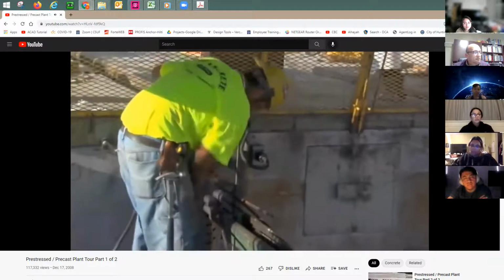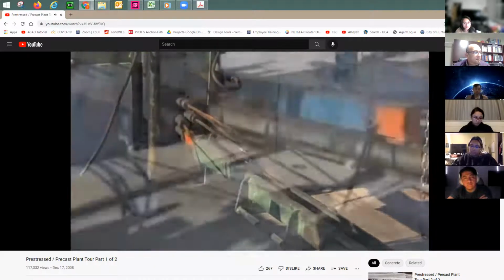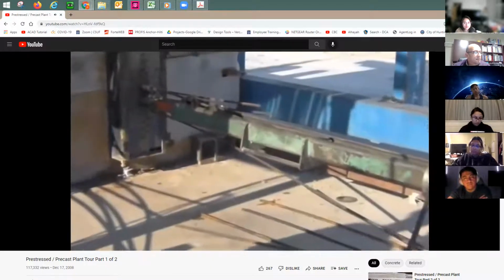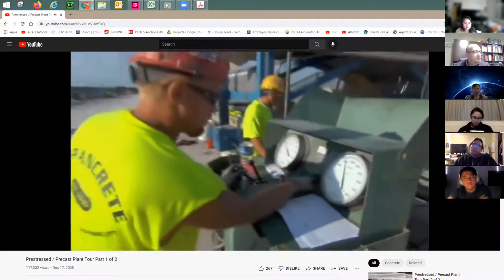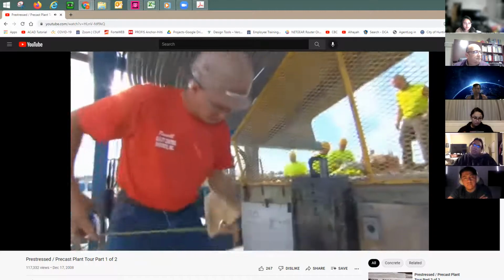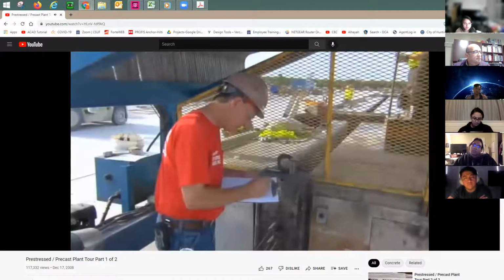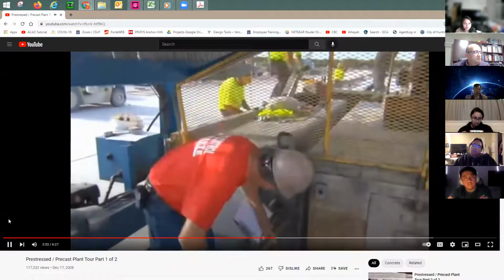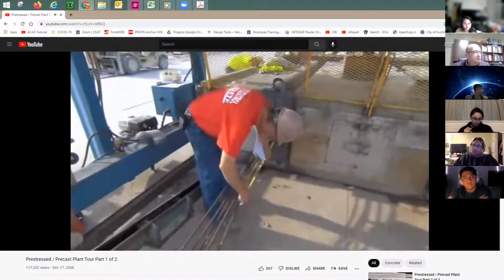In this case, a mark is made on the strand after the preload is applied. The strand is then tensioned to the specified level and is measured using the gauge pressure on the hydraulic pump. The QC technician then checks the elongation against the theoretical elongation. The requirement is that the force on the gauge and the elongation must match within 5%.